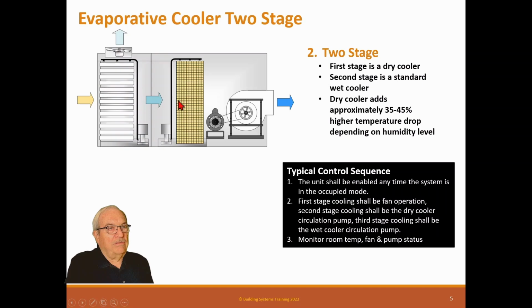It was just too erratic, and you wouldn't think an evap cooler would do that much, but boy, it was cold air when it came out of there because it was real high altitude, and that was return air of the system, so it wasn't that cold. So we had very low humidity at 80 degrees, and it could take that air right down to leaving coil temperature off of a chill water system.